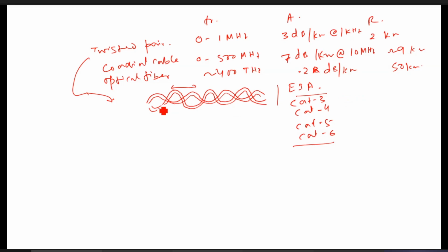Also, this twisted pair can be STP, shielded twisted pair, or it can be UTP, unshielded twisted pair. These are unshielded twisted pair. STP is very costly. Shielded twisted pair is used to reduce the interference. As for applications, STP cables are mostly used in the telephone network, from the telephone exchange to the telephone side. These are widely used, this twisted pair that you know, right?